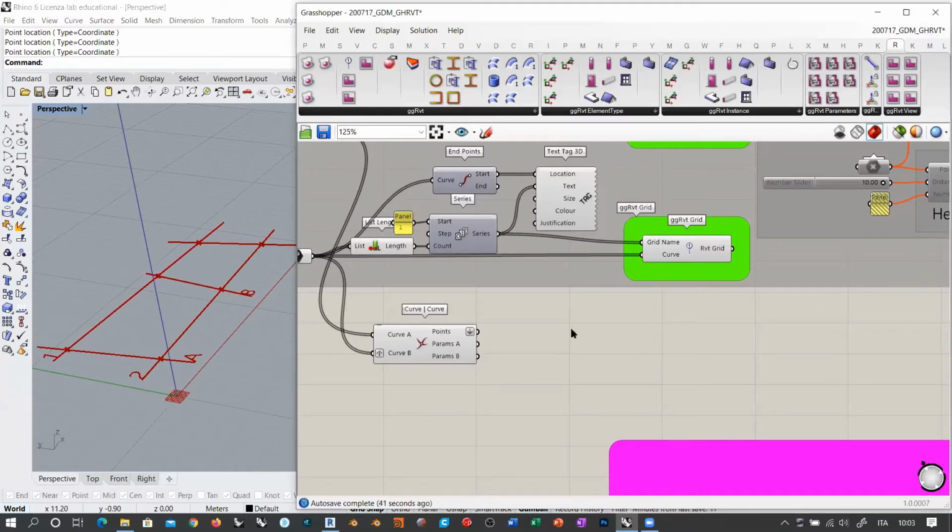So for example, like you would do in Revit, when you want to place a column in Revit, you don't place directly the instance of the column. Well, of course you place the instance, but in order to place the right instance, you must decide what family or what type of column you are going to use, right? And the type of column contains a whole set of properties, which are like, for example, material, manufacturer, cost, and so on.